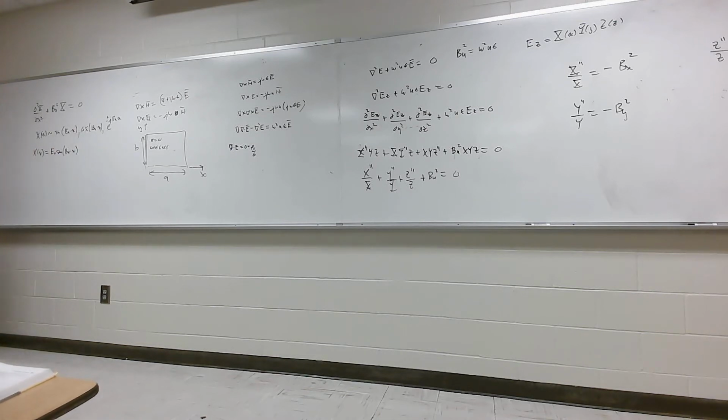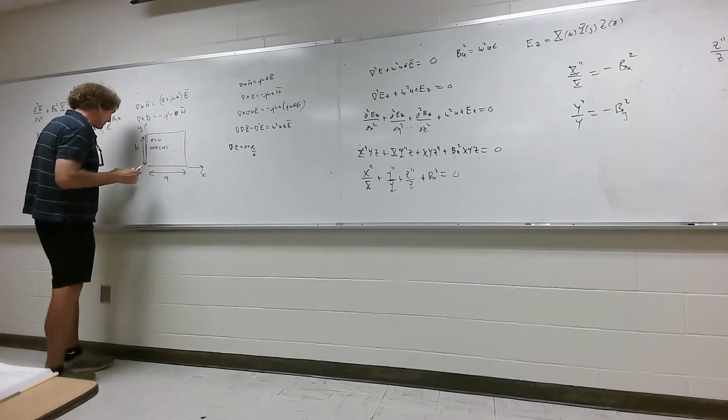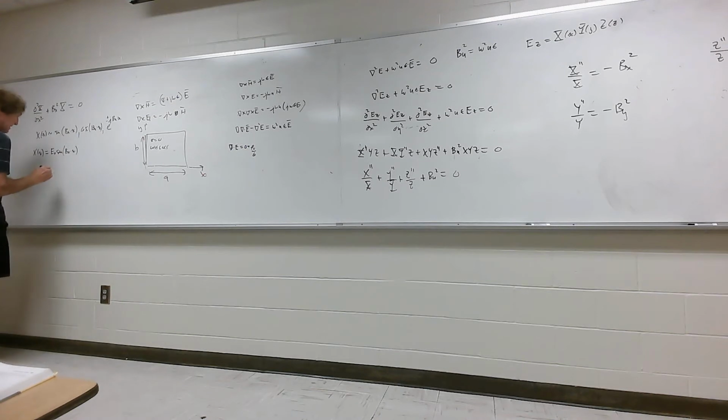Do you remember what the next step was to determine beta x? Y'all realize that works when x is 0, right? It is 0. Where else is the E field 0? At x equals a, right? So that means E0 times the sine of beta x times a has to be 0, right? All right. So this argument is not 0 any longer, right? But when is the sine 0?